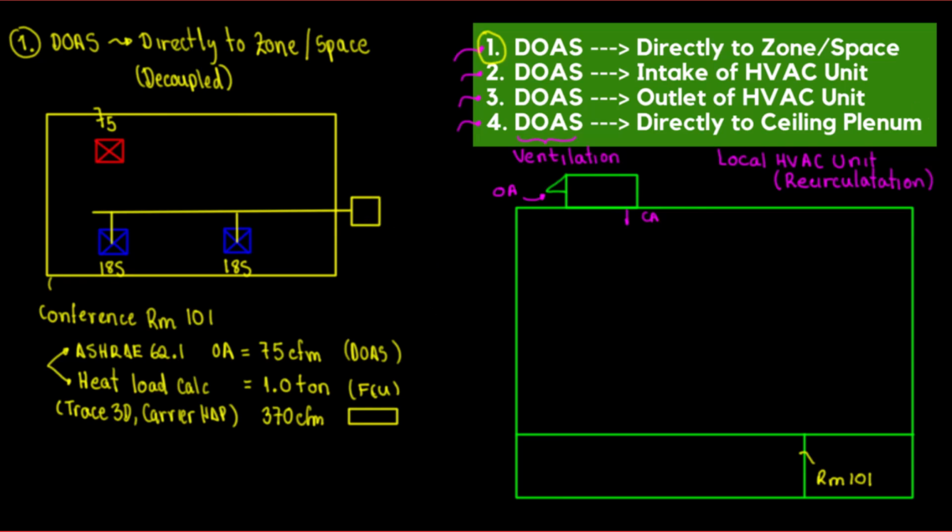It's not the best idea, but depending on coordination with the architect, we can move this in here, and we can move this in here. And remember, this is above the ceiling. There you go. Okay, so in other words, that's going to be my return side. So this is RA, return air. So if it's 385, this should be sized for 370. But someone might be wondering, this is 370 of RA, return air, and this is 185 of supply air. And this is the FCU.